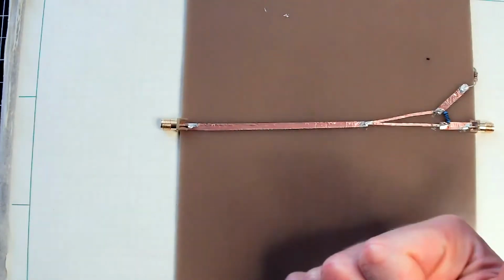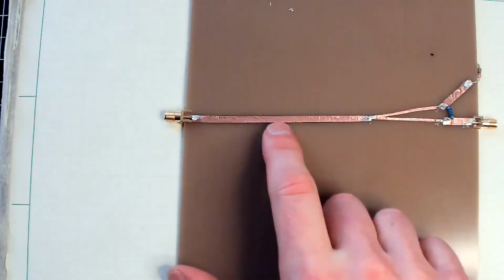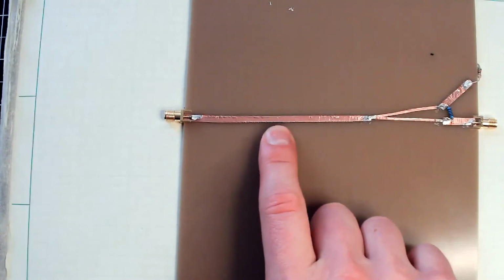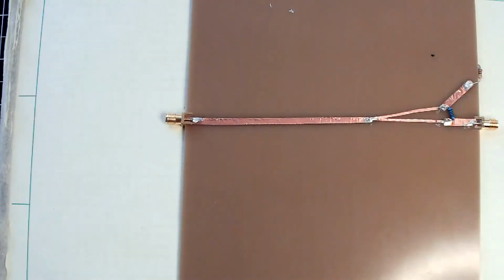Like increase the dielectric or decrease it, or maybe make it thicker or thinner, such that if I want, say, a 50 ohm line, I don't need this 3 millimeters. Maybe I could get away with a full centimeter. Then it'll be so much easier to do this sort of lab project with your bare hands. But that's me looking ahead to next semester for the next batch of 3,300 students. But something to think about, all these parameters that you have control over. So sorry, that was a bit of a tangent.